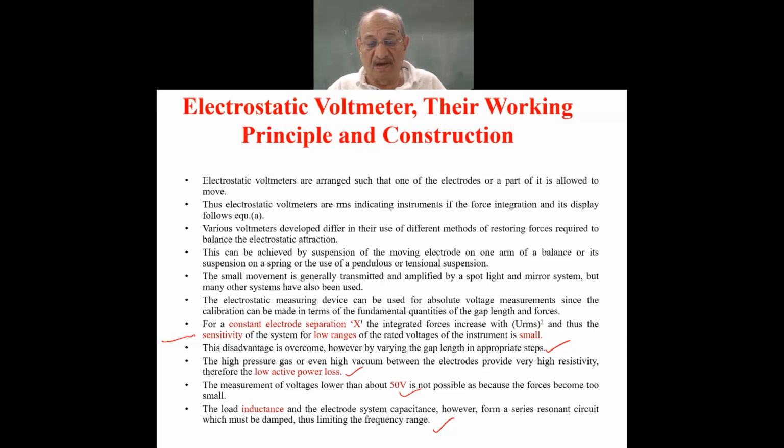So this is how the electrostatic voltmeters work and are being used. And modern electrostatic voltmeters have been constructed with SF6 gas and vacuum, using dielectric instead of simply air.